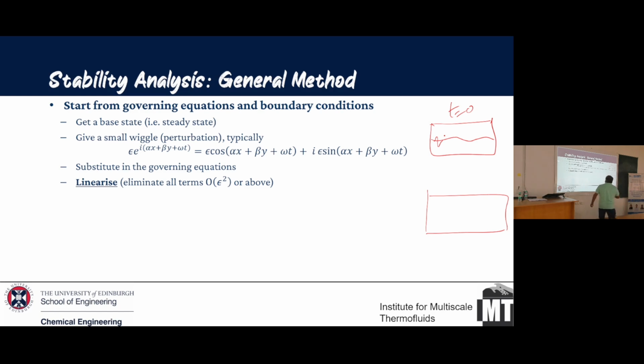But at the same time, you also have the time component here. So it grows with time. Your waves grow not only spatially, but also temporally. So we look at both these aspects. Actually, the real growth rate gives you the wave number, that is the most unstable mode. And the imaginary one gives you the most dangerous frequency. What is the frequency at which your waves would be most active? So both the real part and the imaginary part give you a lot of information there.